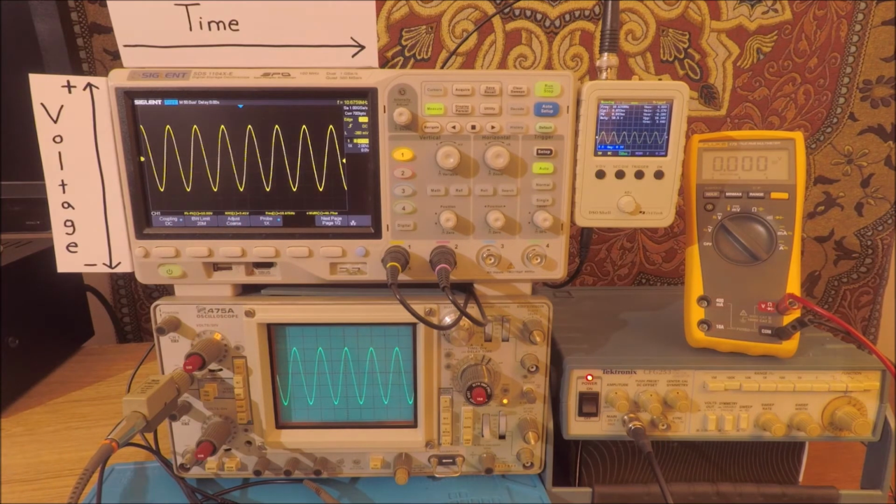The second part of the bandwidth limitation is going to be on the circuitry itself. So in the digital oscilloscope case here, we'll have 4 different inputs, 1, 2, 3, 4. Each of those is going to have an analog front end inside the oscilloscope, as well as an analog to digital converter. Those 2 pieces of circuitry combined are going to control what the overall bandwidth of the scope was, in this case 100 megahertz. Same thing on the analog scope, except it's going to be the analog circuitry alone that will determine that bandwidth.